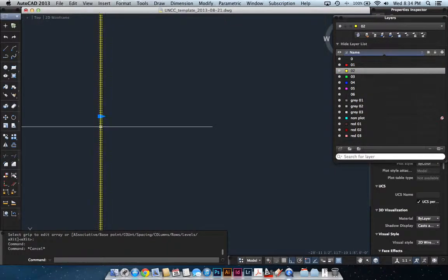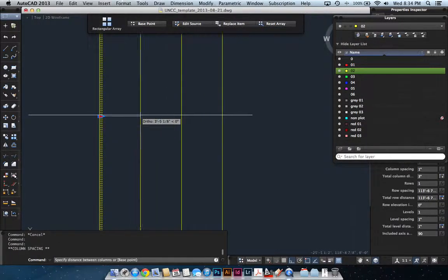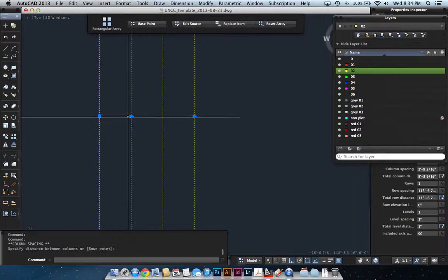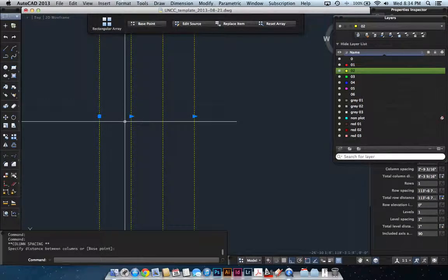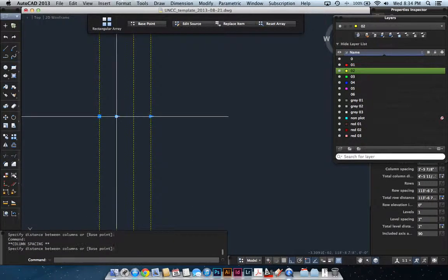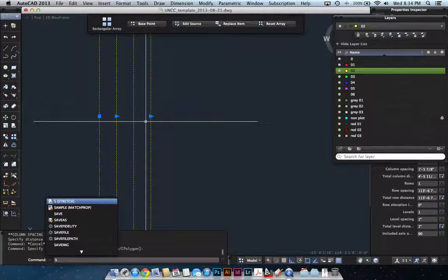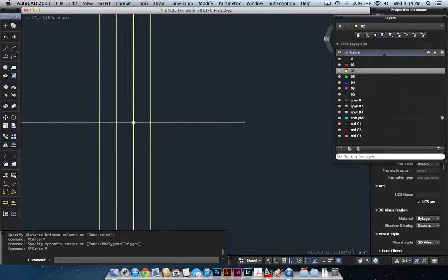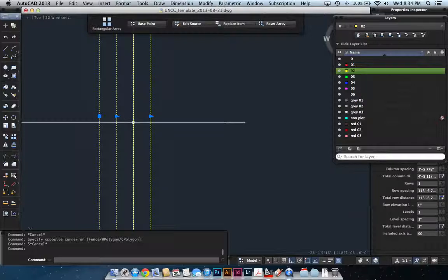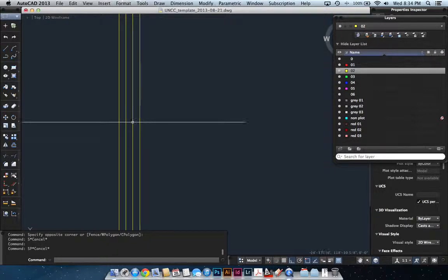Well, if I go and select on the object, one of the things that comes up when you're actually in the edit mode is this idea where you can start to stretch the columns apart, and you can do that manually by just grabbing the grip that's here, this arrow piece, or you can actually take on the idea of the spacing and you can start to edit the actual space between the lines themselves.